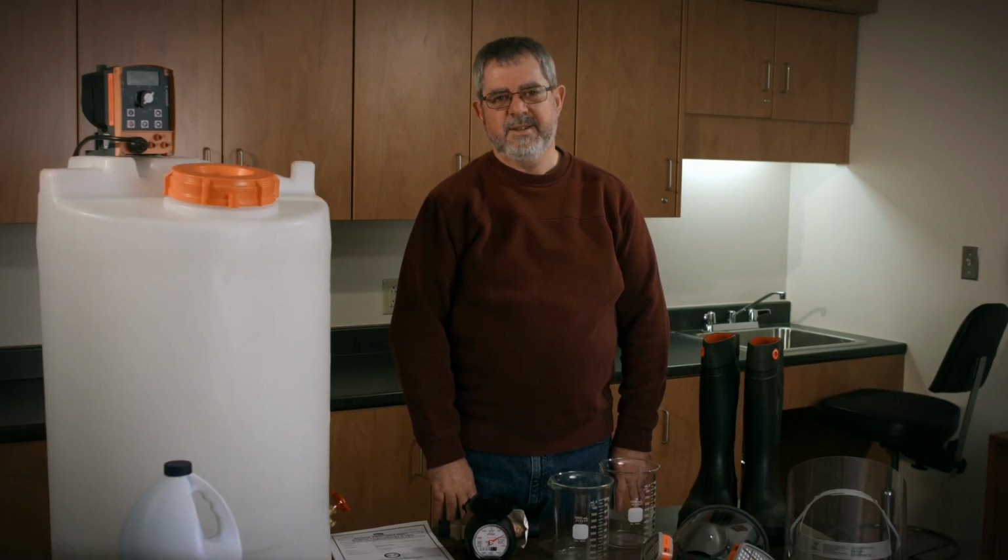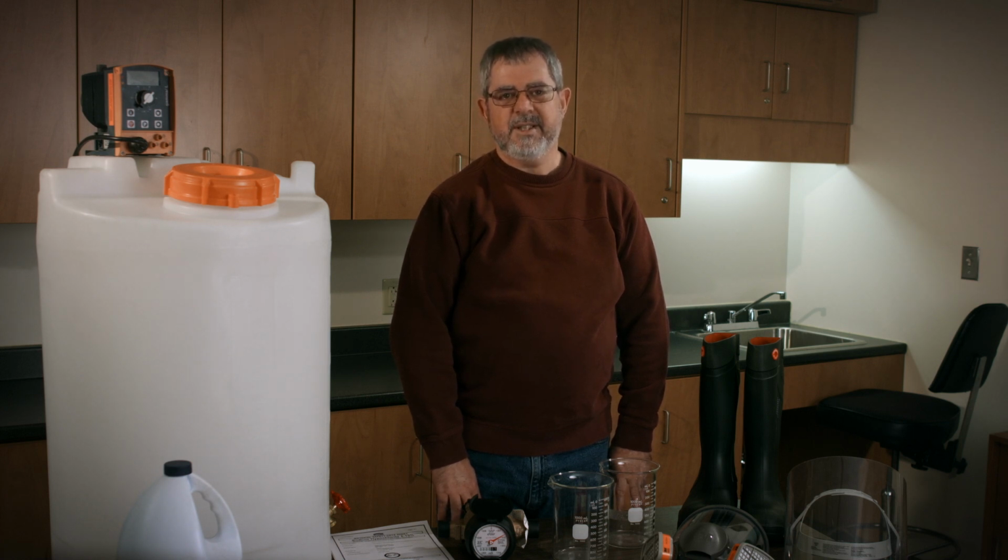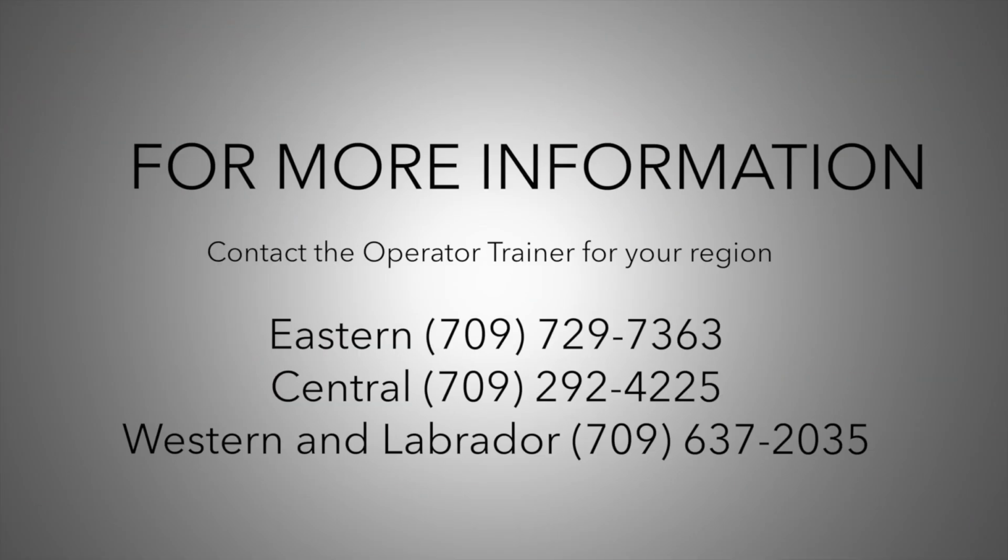The hypochlorination system is now ready for operation. It should have the optimum solution concentration to control the chlorine residual during operation. Any adjustment of the chlorine injection should only be made using the stroke knob or the injection rate programming in pumps with this type of electronic control.